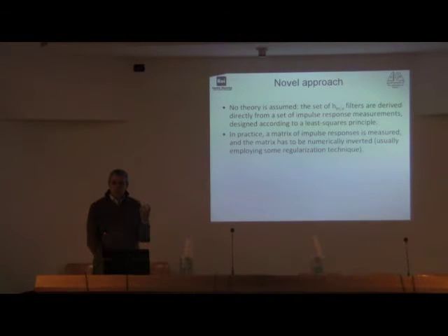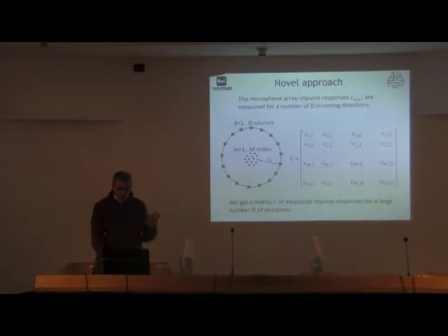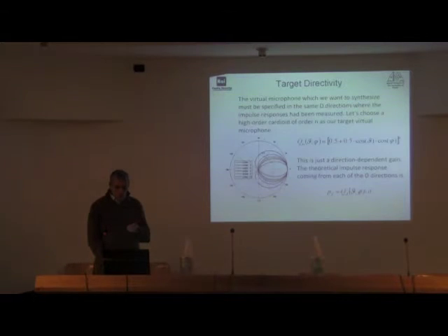We measure the impulse responses of our microphone. We get a matrix of measured impulse responses. We invert that matrix, and that's all. I am not going to explain all the details here. You find them in my papers. So we go very quickly over the slides which describe the measurements of the impulse responses of our microphone array. This is our target directivity. Our virtual microphone is designed to be a cardioid, or a high-order cardioid.